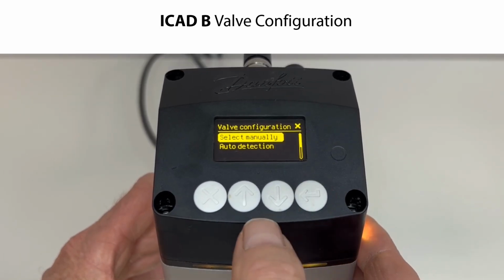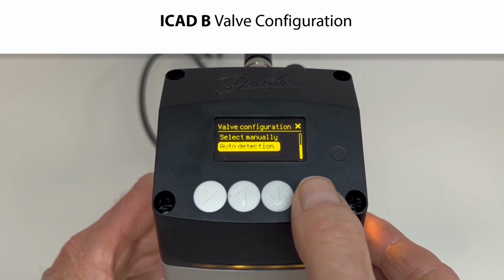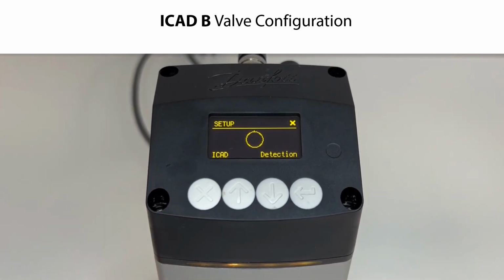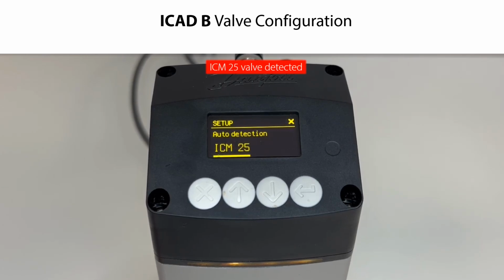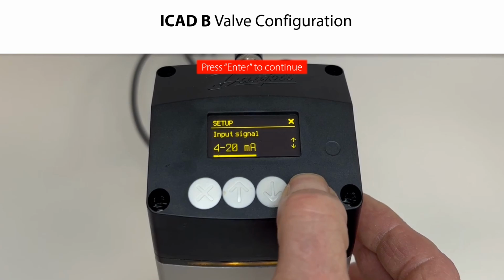The next step is then to configure the valve on which the ICAD B is mounted. As seen, here you can select between manual valve selection or automatic valve detection. In this example, we select auto detection. Press Enter to confirm this. The ICAD B will now automatically detect and configure the valve onto which the ICAD B is mounted. As seen here, then the ICAD B has detected and configured an ICM25 valve. Please see more details about valve configuration later in this video. Press Enter to continue the setup.